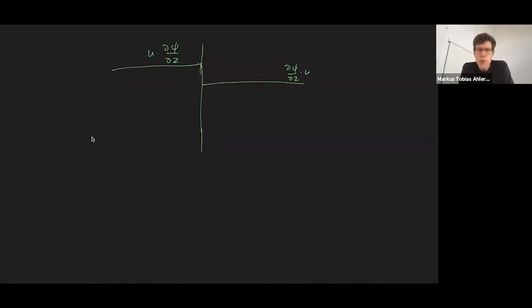So the only thing that we need now is if we are integrating here across the shock from minus epsilon, which I call O minus, to plus epsilon, which is O plus, then if these two quantities are real valued, so well-behaved quantities, then as long as this integration region goes to 0, the contribution of this term is going to be 0, independent of how this exactly looks on both sides of this shock. Is that clear?